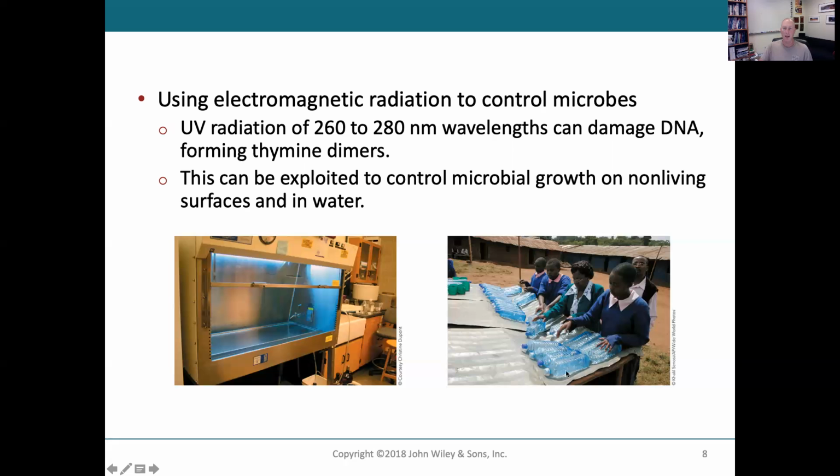You can put your water in a plastic bottle and expose it to sunlight for usually 2 to 4 hours. The sunlight provides UV light. Often the best way of doing it is to put it on top of a metal roof like this. These sort of corrugated tin roofs are common in poorer countries, at least in some places. And so that roof also heats up. So you have a combination of heat and UV that is treating this water to disinfect any potential pathogens in it, whether they're viral or bacterial or whatever.